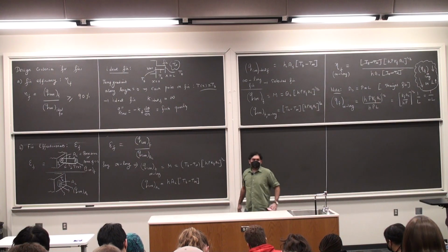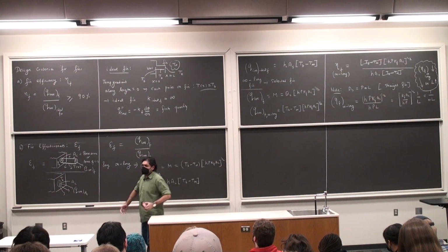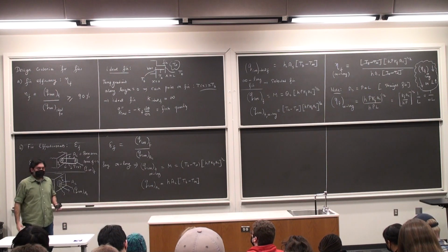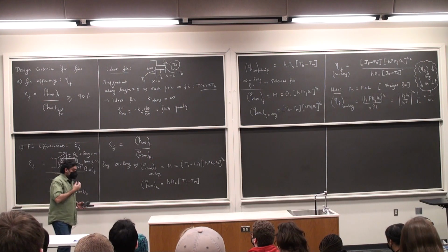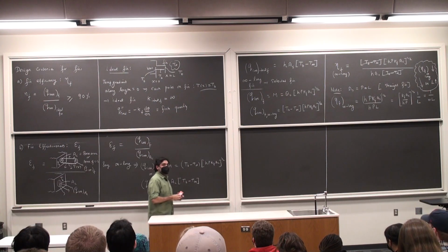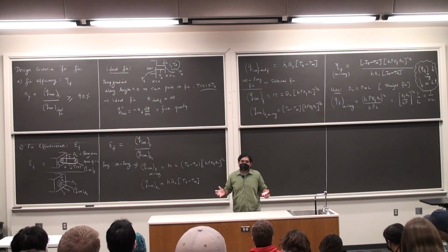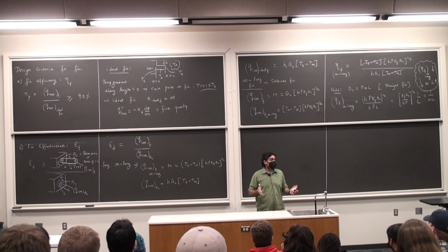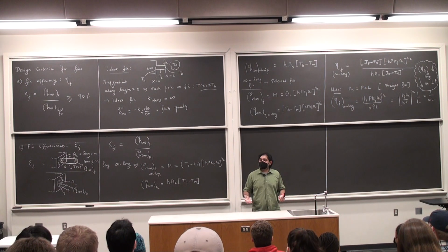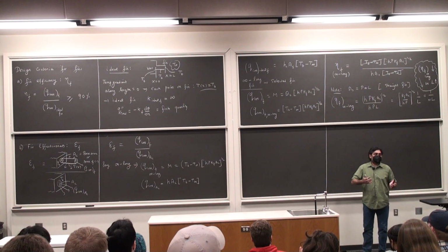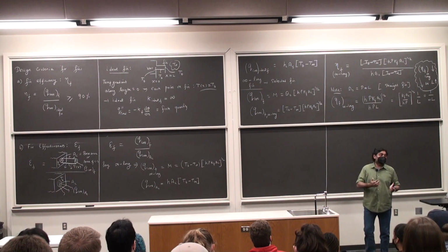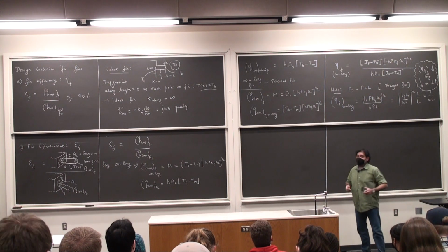Does this make sense to everybody? This is very practical, right? What's the use of a fin? It has to cool things. If I'm using a fin and the cooling efficiency I'm getting is like 20% and the effectiveness is 0.05, then I'm essentially increasing my space, adding some extra components which increases the weight, and this is an absolute waste of my time. So I want to redesign this and see, are these parameters satisfactory? If they are, then it's worth it.